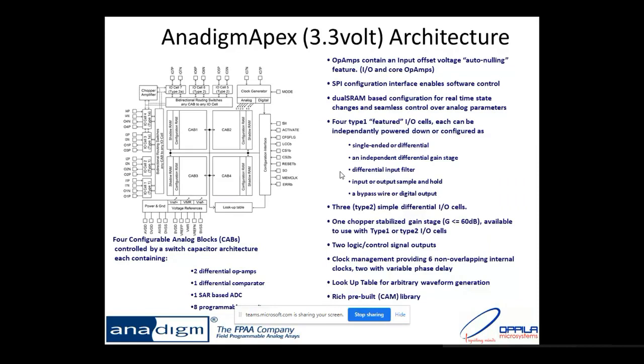How does this microcontroller get programmed? This microcontroller is communicating with our PC through the USB cable. You have connected one USB cable between the PC and your FPAA board. Through this cable, the AnadigmDesigner EDA tool communicates with the microcontroller. We design a circuit inside the EDA tool and feed it to the FPAA board. The EDA tool gives data to the microcontroller, and the microcontroller gives the command to all the FPAAs.